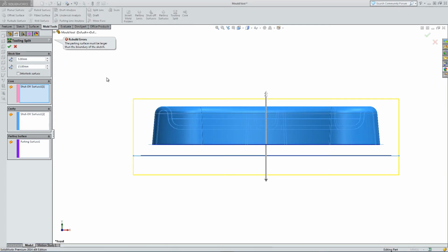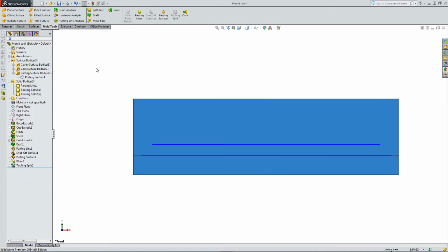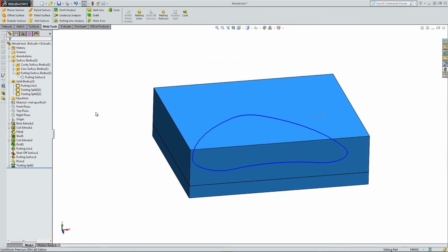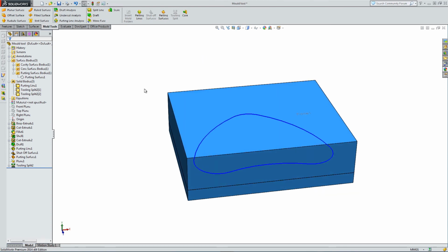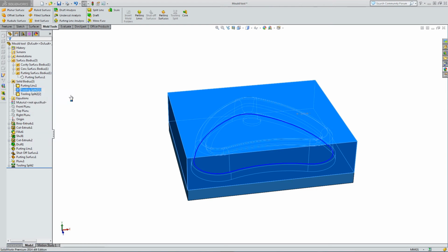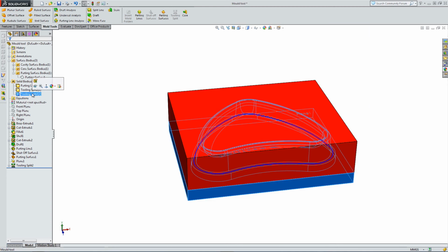So everything we've done now is basically prep work to make this work. So I've not selected the interlock surface, so we need an interlock surface, and that just gives us a slight offset from the plane that we've drawn from, and 3 degrees gives us a slight taper on that. Okay, so it's worked. So it doesn't look very exciting, it looks like we've just drawn a block, but there's more to it, I assure you. Let's change the colours so that we can see more clearly what's going on here.